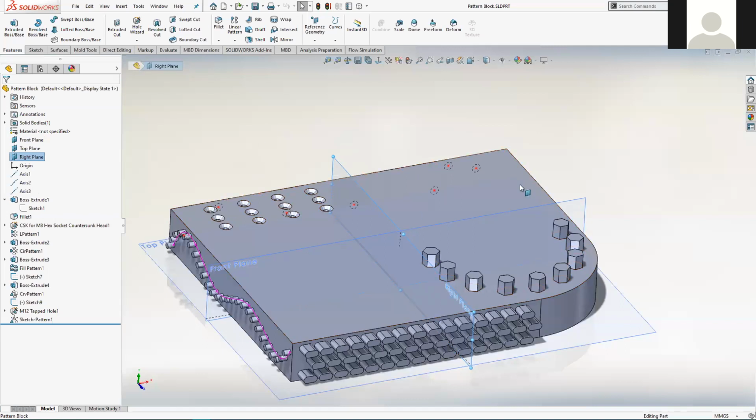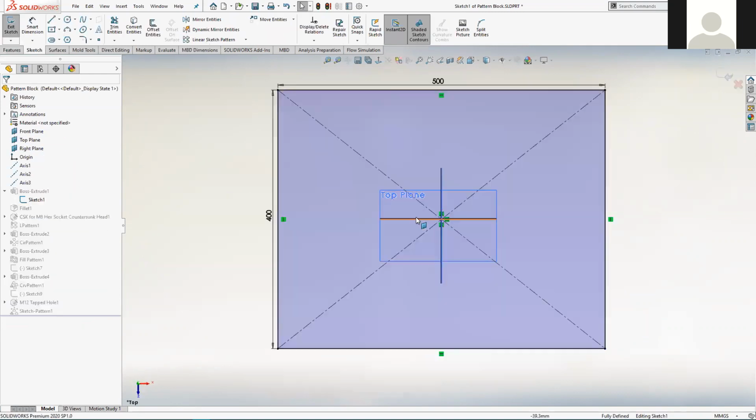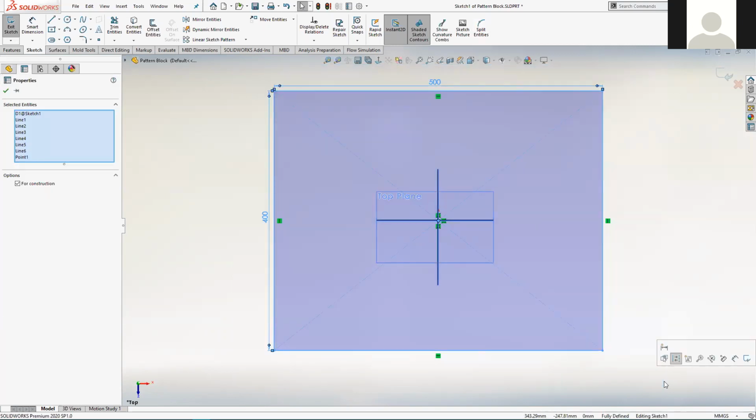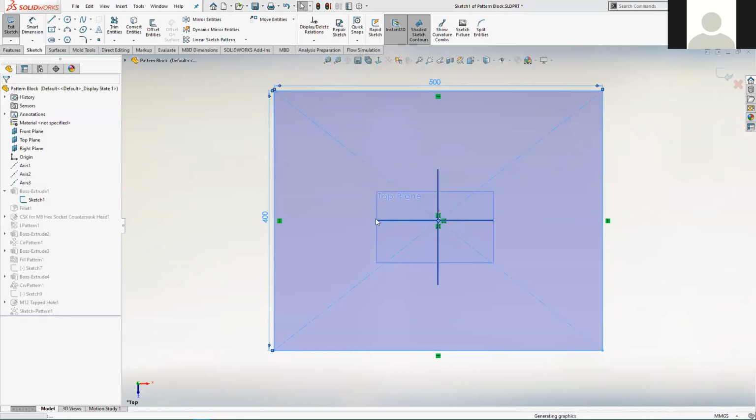And that's because any changes to your model have the potential to ruin other features. And you saw a good example of it there. I played around in that initial sketch to such an extent that the system didn't understand that the new rectangle shape that I created wasn't the same rectangle. It saw it as an entirely new shape. It didn't realize that I'd just replaced old for new and they were identical. It doesn't work like that. So the fact that I deleted all this sketch initially to show you how to create it meant that the rest of my part failed there. So yeah, that's sort of a word of warning.